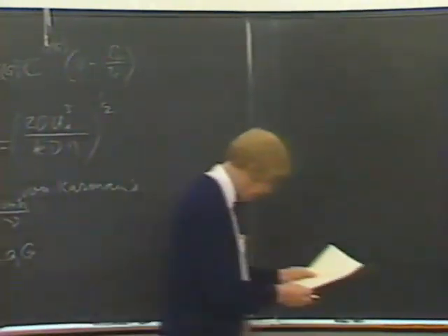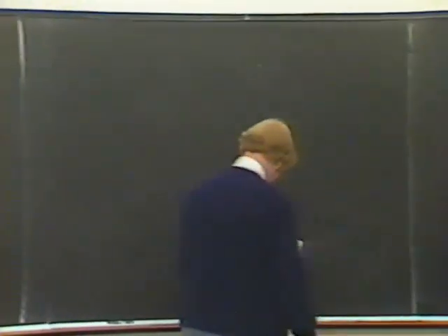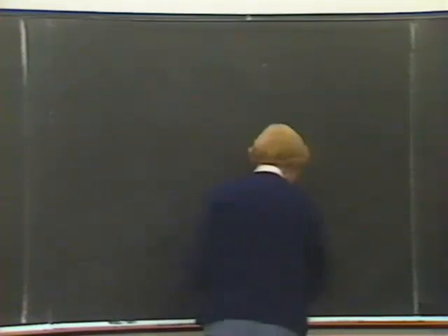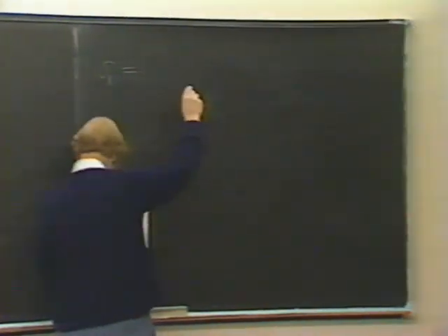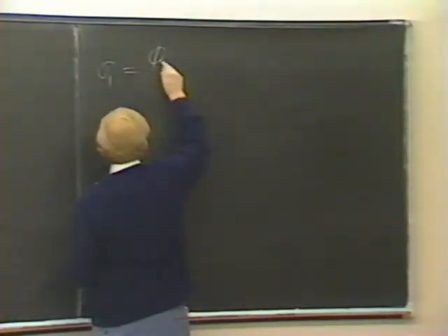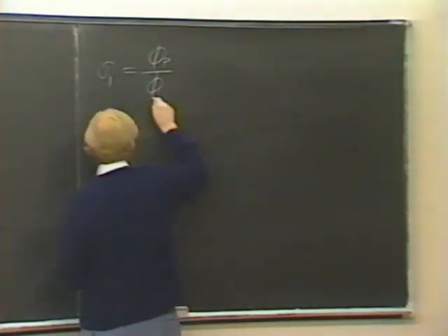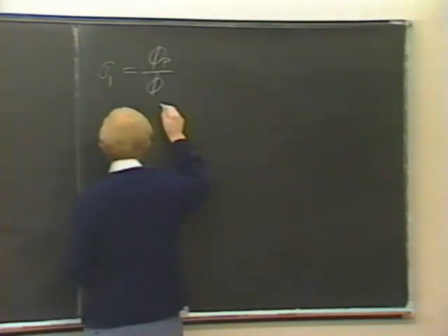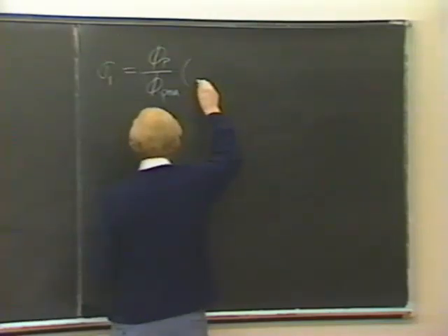We can say that the downward force, I'll call it sigma 1, according to geotechnical procedures, is equal to the volume fraction of the particles divided by the volume fraction of the aggregates, I'll call it Vp and Va, times (rho P minus rho L) times G times H, and I'll call this H the distance into the bed.